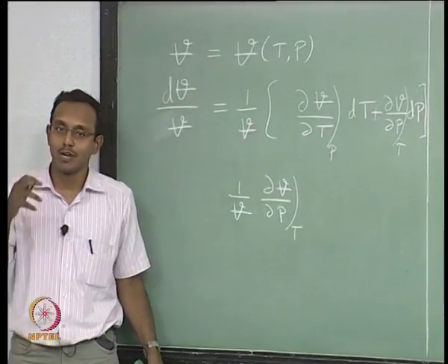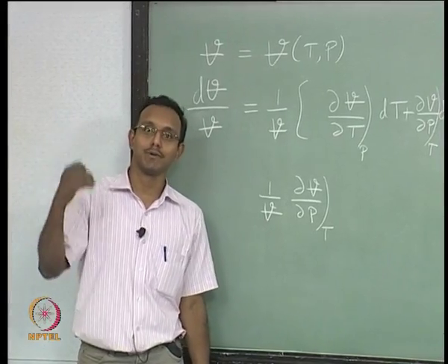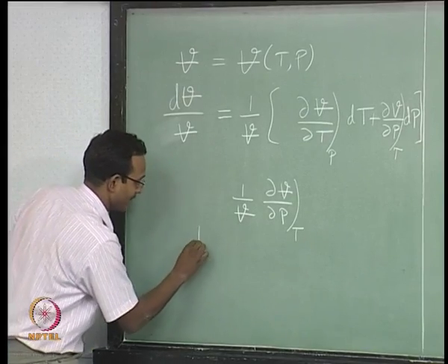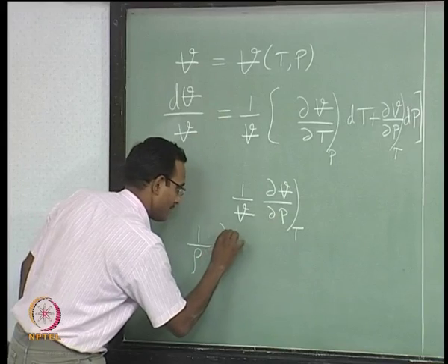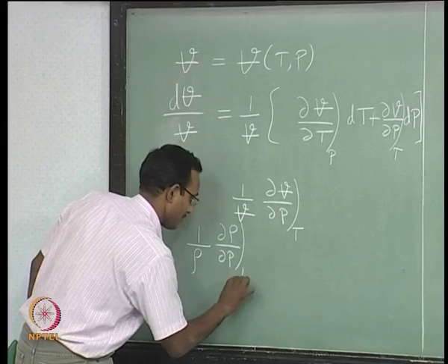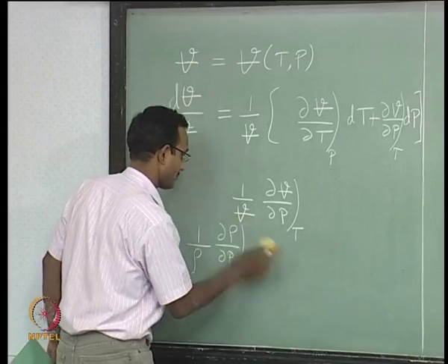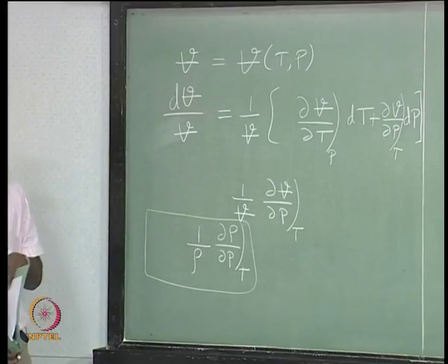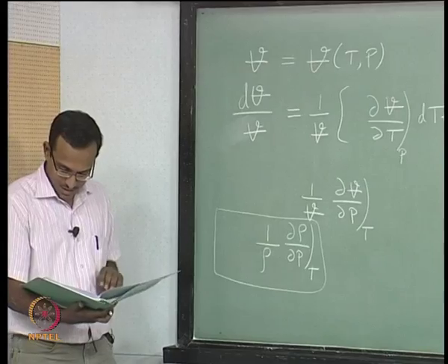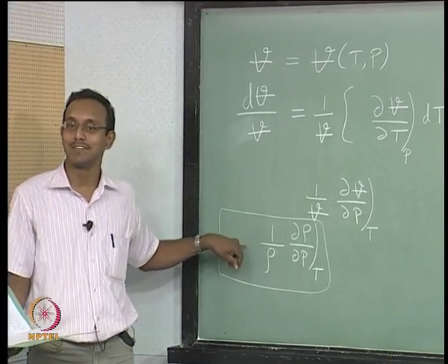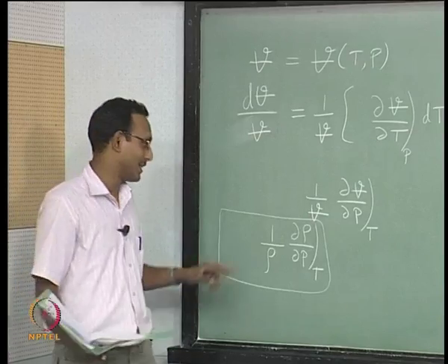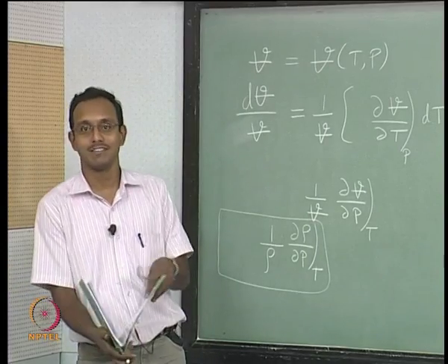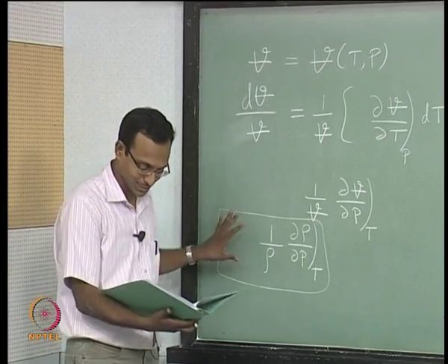What is specific volume? It is volume per unit mass. Density will be mass per unit volume, just reciprocal of it. I can write it in terms of density. Compressibility can be defined as this. Okay. This is also probably called compressibility, whichever way you look at it. Okay. In most of gas dynamics, we will think about this. This is easier to work with. So, we will typically think about density of a gas compared to specific volume of a gas. It is equivalent, just one is a reciprocal of the other. We will stick to this.